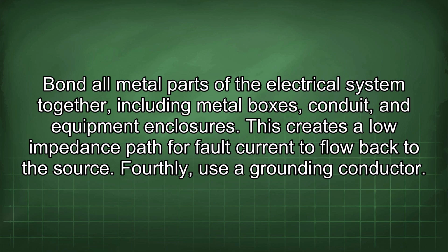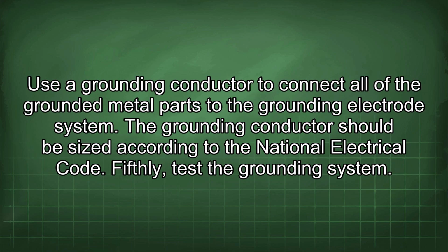Fourthly, use a grounding conductor. Use a grounding conductor to connect all of the grounded metal parts to the grounding electrode system. The grounding conductor should be sized according to the National Electrical Code.